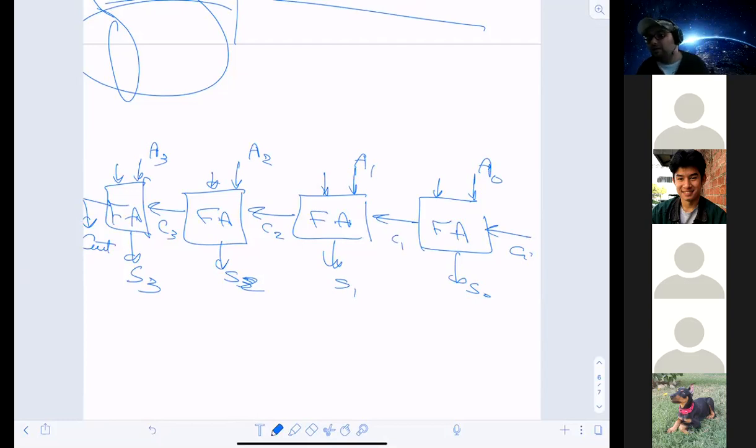How? We learned in our study that there are things called multiplexers. You agree? So I can do it like this: a multiplexer having B0 in the 0 location, and in the 1 location the negation of B0, and there is a selector.